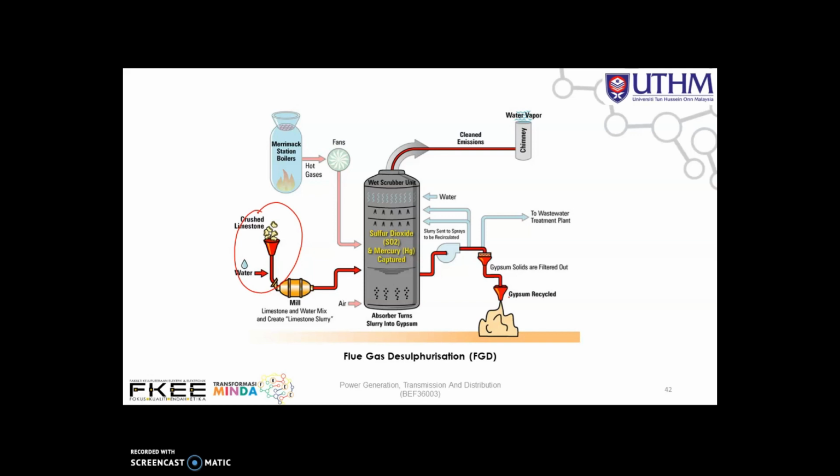So the wet process has become the main method of FGD in large fossil fuel power plants. In this method, the flue gas is steam saturated with the absorbent in aqueous solution. Normally substances such as ammonia, sodium sulfide, lime or limestone slurry are used as the absorbents. So the unclean flue gas is sprayed in a scrubber tower, the absorber tower, with a mixture of water and limestone, whereby most of the sulfur dioxide is bonded by the chemical reaction.